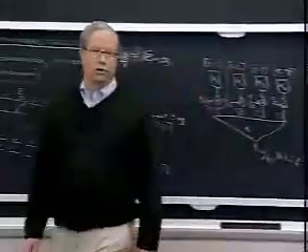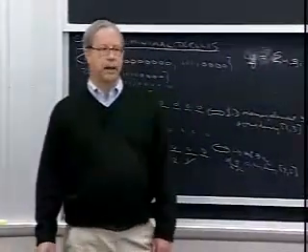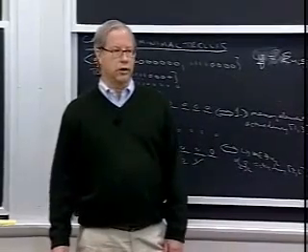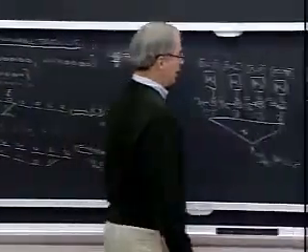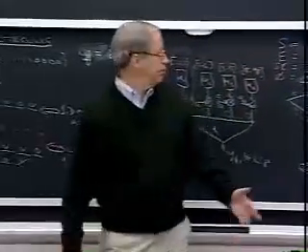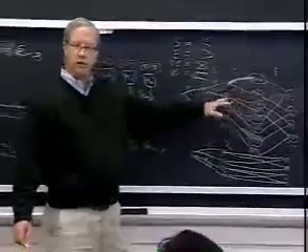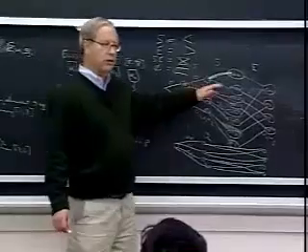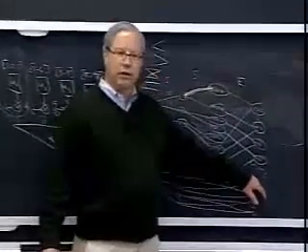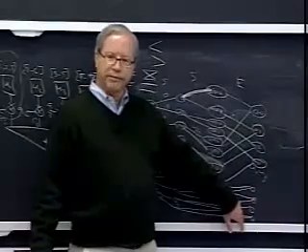Okay, that looks only like a 4-state trellis. Now, is this still a legitimate trellis? Yeah, it's still a legitimate trellis. If I do a Viterbi algorithm decoding of this trellis, is it any different from this? Well, in detail, it is a little bit different. You do the additions and the comparisons and the selections. You only do selections every this often.